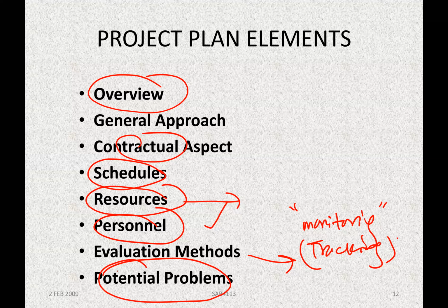Planning is for the future. Why? Because we want to reduce uncertainty. Let's say we want to do a big casting in a certain area, we must be thinking, can the concrete batching plant supply that huge amount of concrete within a short period of time, in a few hours? Because normally when you do a big casting, you do not want to stop. It will go on and on for a few hours. It will be maybe, I don't know how many cubic meters of concrete that you need.